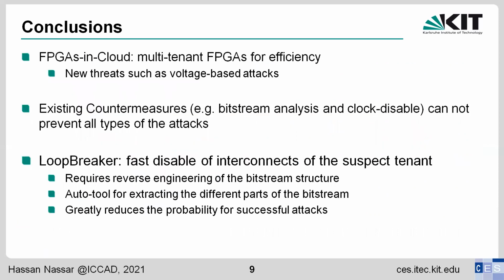To conclude, in FPGAs in the cloud there is the threat of voltage-based attacks, and the current countermeasures are not enough. That's why we proposed our solution, which uses a fast disable of the interconnects to stop the attacks.